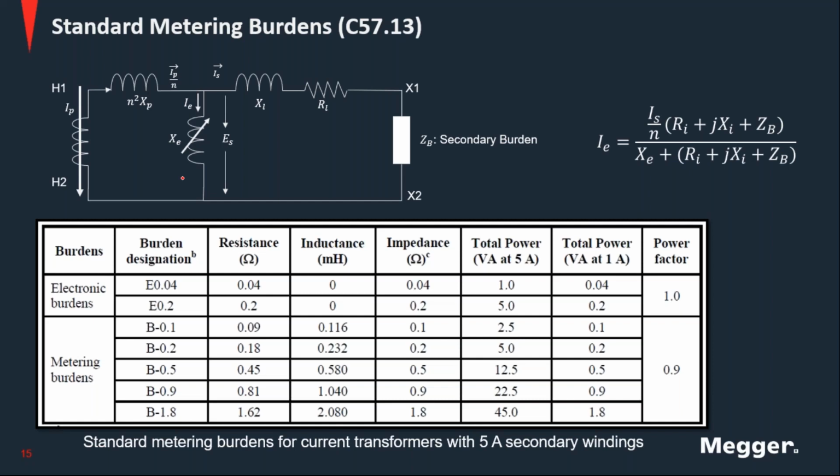Other things have been mentioned here. For example, you do a winding resistance test on the CT and you don't perform a proper demagnetization, or sometimes you do perform the demagnetization, but some CTs have too much core, and the demagnetization doesn't work as intended, and then you will have problems with the increase in the excitation current. So there are many different factors that can increase the excitation current, and I have just mentioned a few of them.